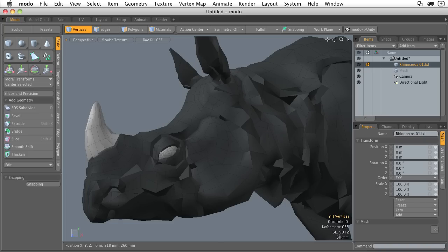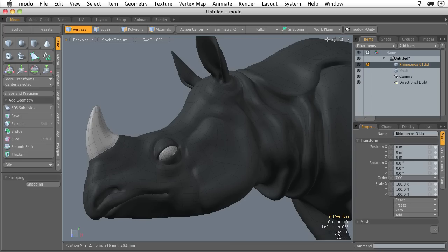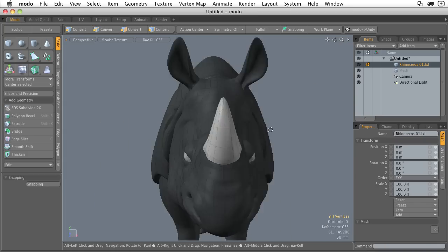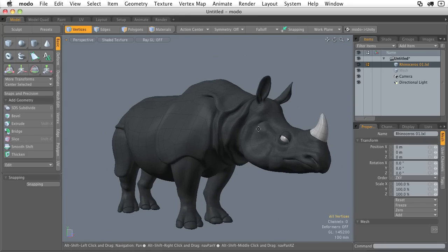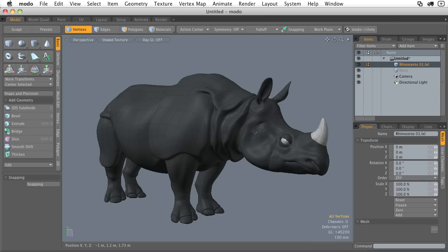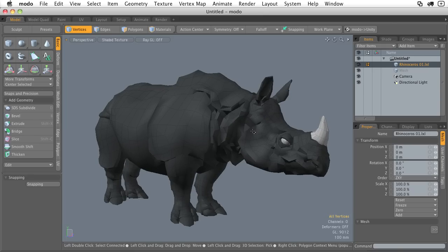Now, most importantly, if we hit tab and go back to our polygonal cage, you can see that the OpenGL meter here is solving 9,012 polygons. If we hit tab, though, we're now taking a big hit. Since we're creating the illusion of a perfectly smooth surface, we're now being hit with 145,000 polygons. So subdivision surfaces can take a little bit longer to render, but creating the initial shape, creating the base model for our rhinoceros, is relatively easy using our polygonal tool set.